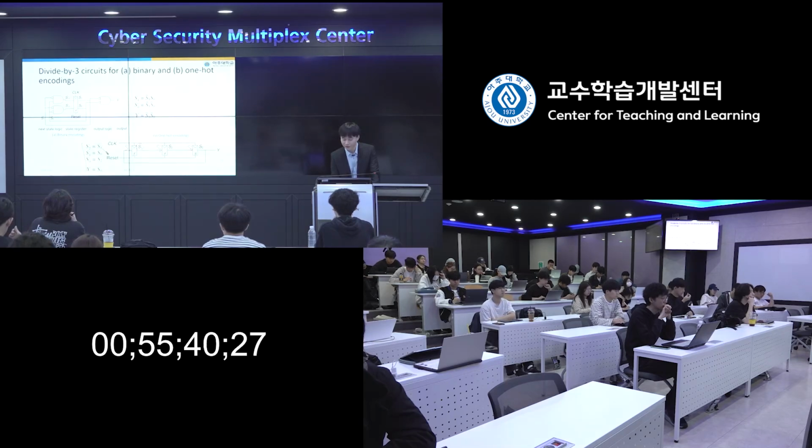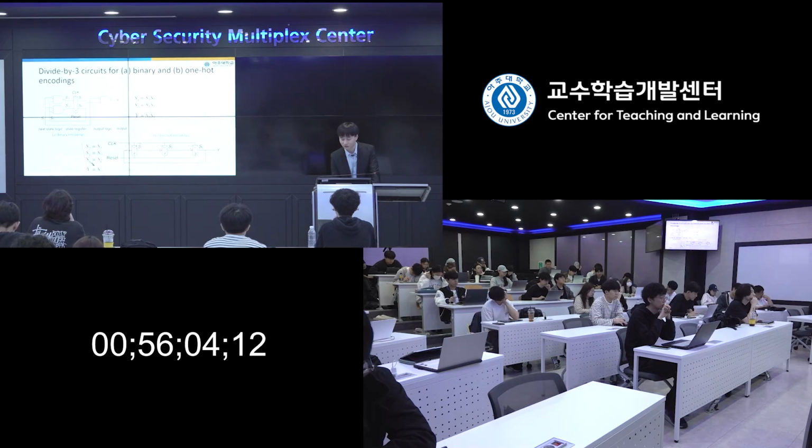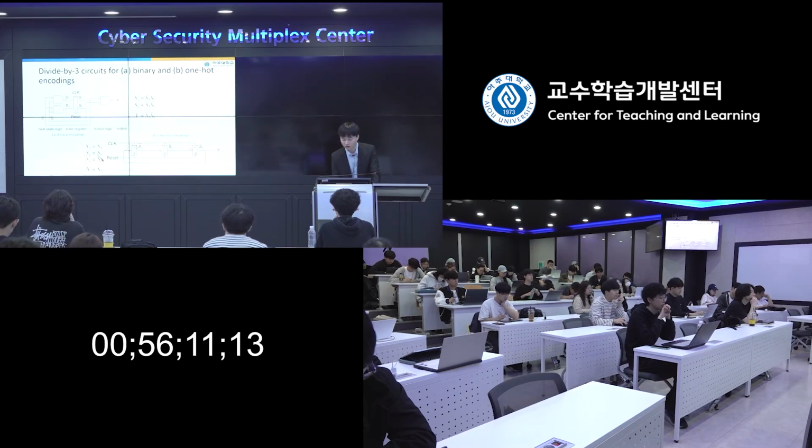Then you have an S1, you draw 1 register, and its output forwards the input data to the second register, which is S2 prime. S2 prime will generate S2, then S2 goes to the third, where you draw another register, which is S0 prime, then output S0. S0 is fed back to S1 prime.